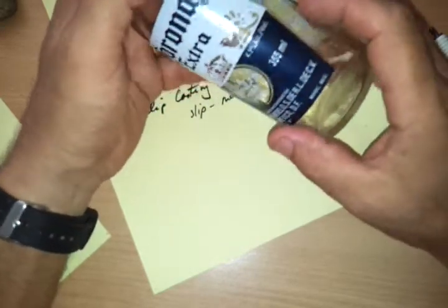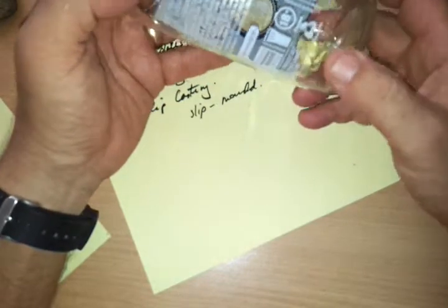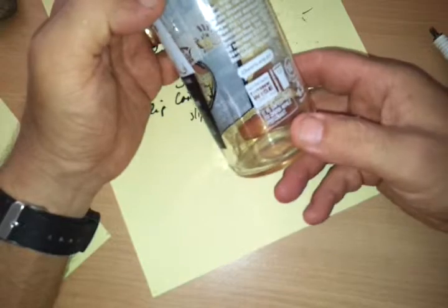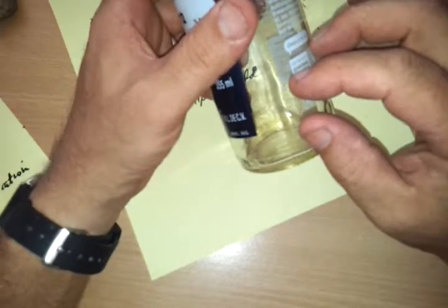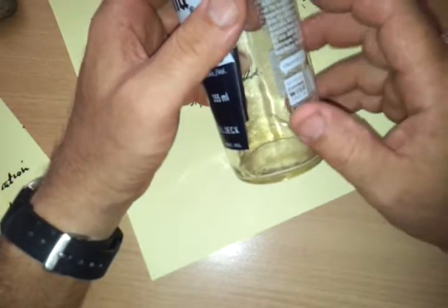Now, the other property which glass has is that it's non-corrosive, and it's very easy to manufacture. And there's lots and lots of raw materials around to make glass, specifically silica. It has no repetitive structure. Most glasses don't have a repetitive structure. They're non-crystalline, which means they're called amorphous structures. So that's important to remember.